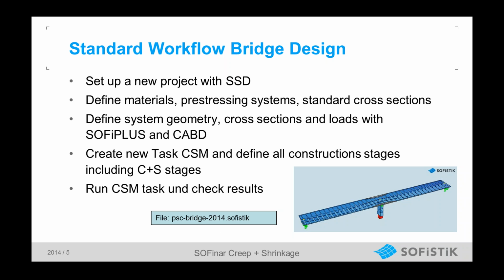The standard workflow of a bridge design with SSD and SOFiPLUS is, I think, well known by everyone. As I look at the attendee list, we have lots of experienced users here, so you know exactly how to set up an SSD project, define materials, and define standard cross-sections. Then you switch to SOFiPLUS, where you define the bridge axis, bridge placements, and the master cross-section, again with variables following the bridge axis.